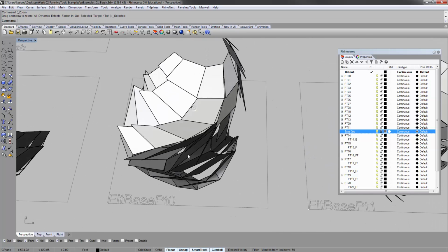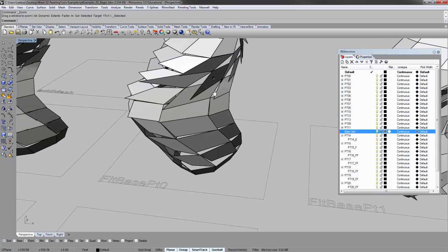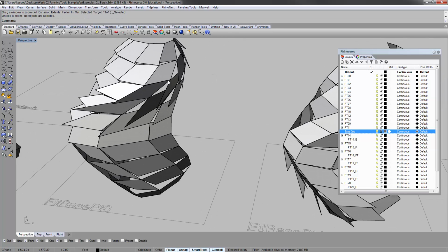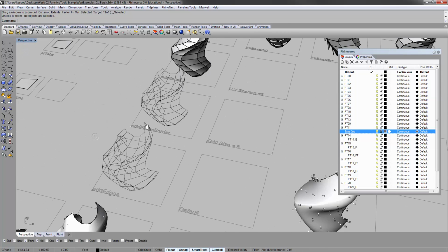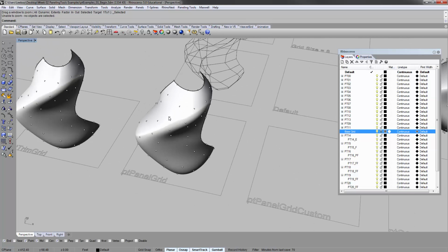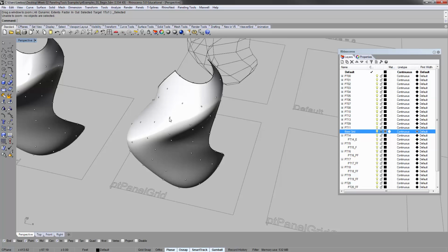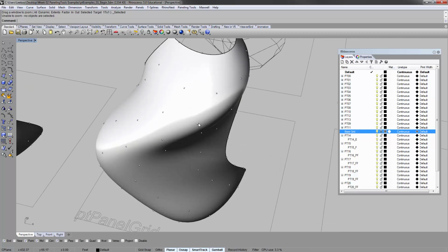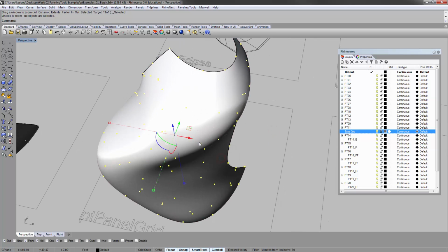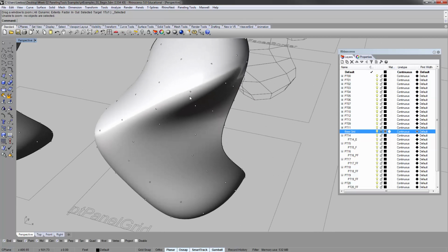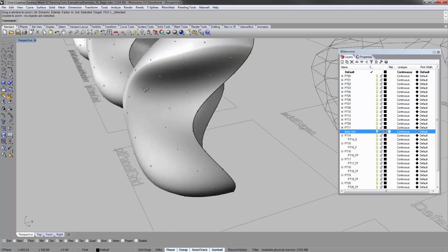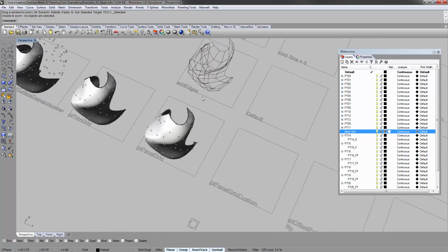All of these are different versions that use one of the 4 vertices of each panel and the surface curvature of the original surface at that point, and use that to determine the direction, the inflection, the angle of each particular panel. And obviously for each one of these panels, the direction the surface is going at this point versus that point from the 4 corners of the same panel are going to be different, right? Because they're facing different directions.